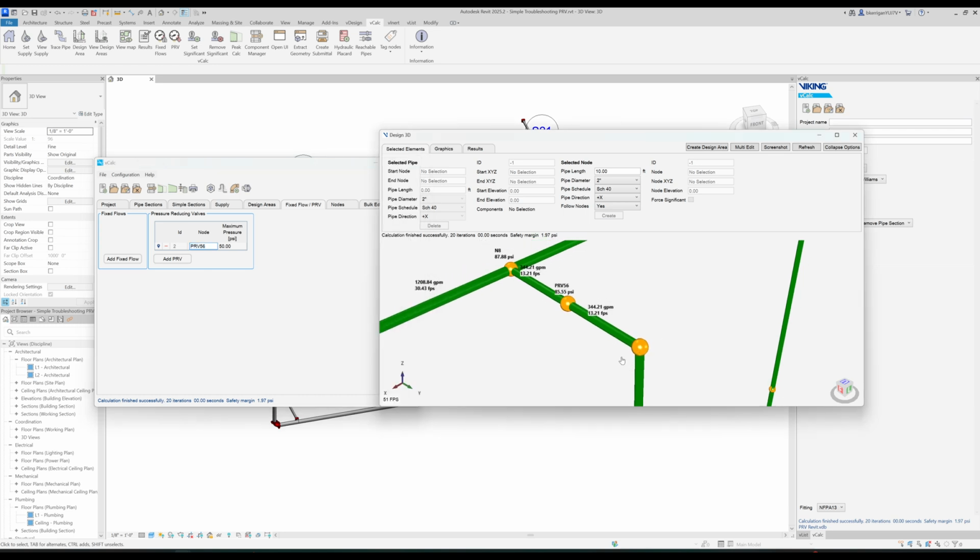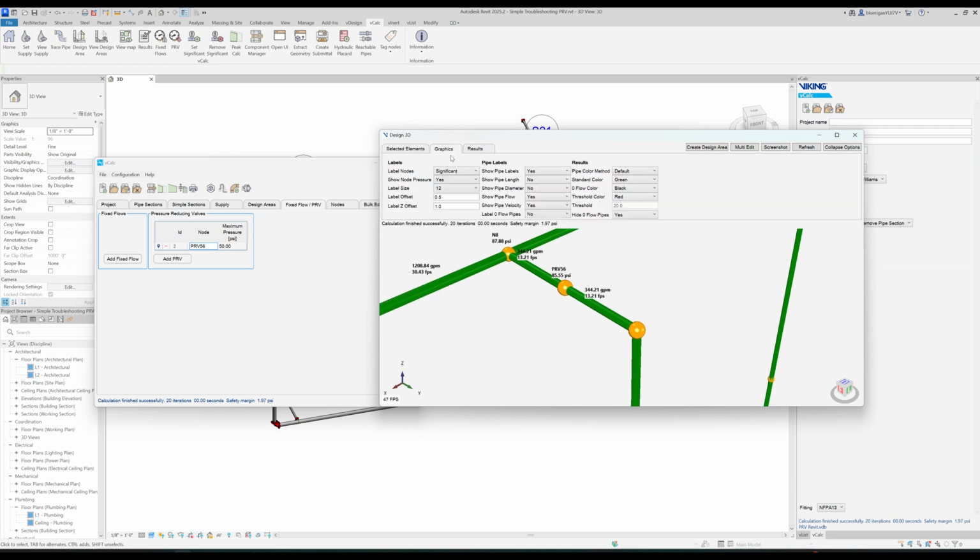But what it's going to be doing is limiting all the downstream pressure. So all these nodes after that are going to see this as if it was operating at 50 psi at this node, and we can already see that it dropped our flow requirements as well, because all those heads downstream are seeing a lower pressure.